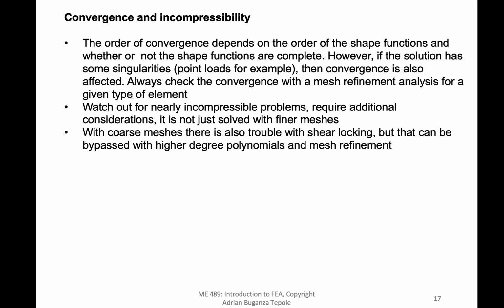You are at machine precision, and the solution is just not changing. That's something that you have to do when you are doing a simulation. You want to check that your mesh is fine enough such that there's no more change in the solution if you refine the mesh. However, in some cases, your solution might converge, but it will converge to the wrong solution.